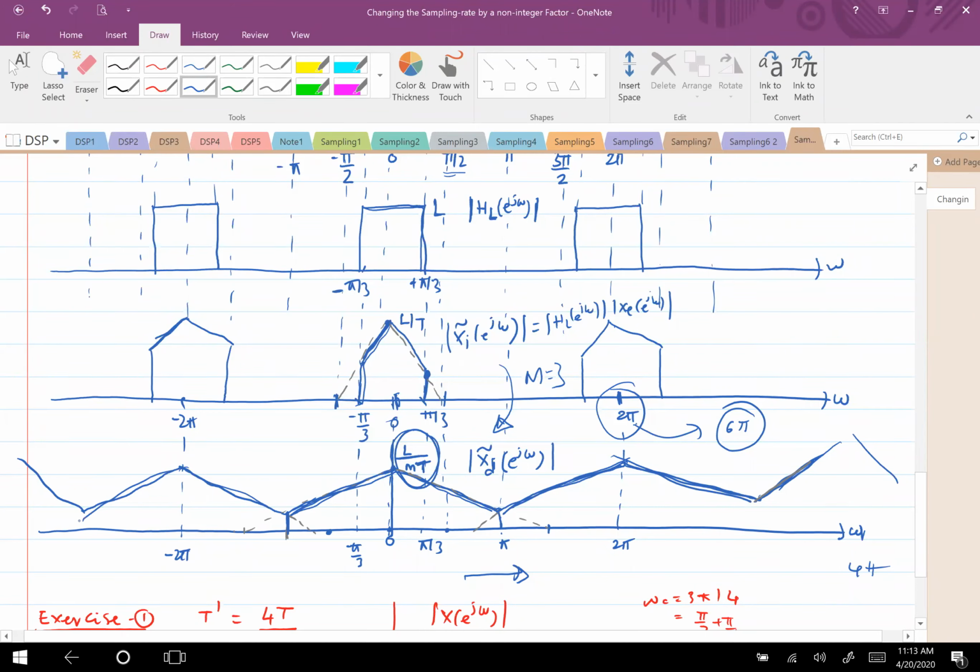So whether you are getting it or not, don't use it for drawing it right away, not trying to interpret the concepts, but rather use it as a cross check at every point. You could use it while you are downsampling. You could use it while you are upsampling. You could do it while you are converting a continuous time signal to discrete time signal. The simple principle that the signal should be periodic with a periodicity of 2 pi.